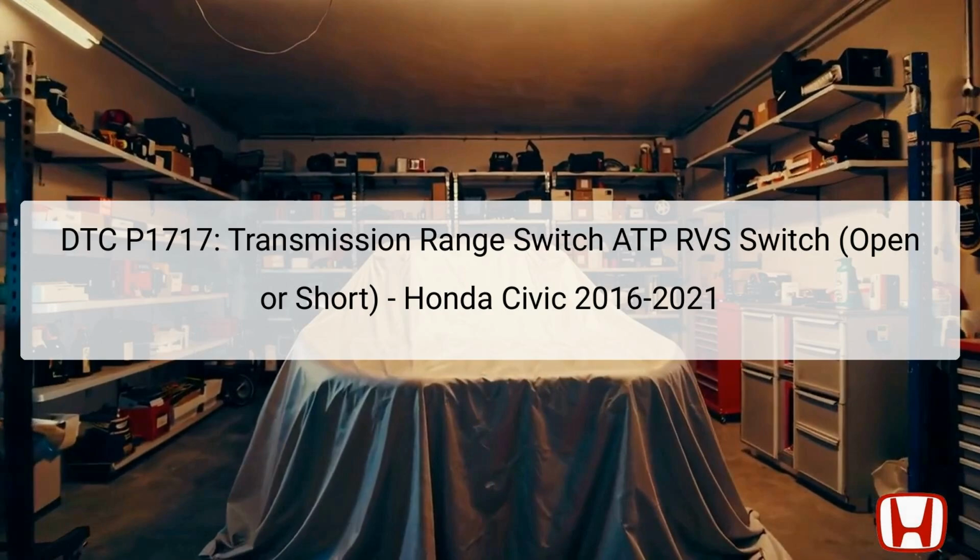The Diagnostic Trouble Code DTC P1717 refers to an issue within the transmission range switch ATP RVS reversing switch on Honda Civic models from 2016 to 2021. This code indicates either an open or short circuit condition that affects the functionality of the transmission range switch, which is essential for signaling the current gear position of the vehicle.